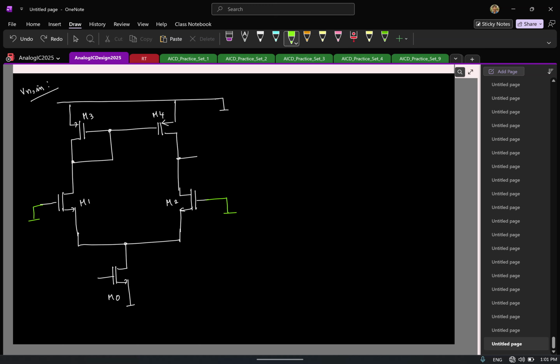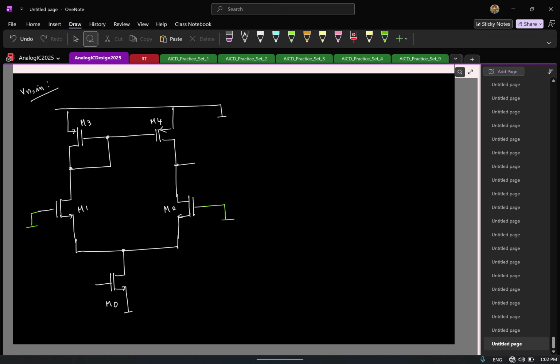Great. So the exercise is the same. How many noise sources are here? 5 are there. So you find the noise from each of these 5 transistors to the output. Here the short circuit current is easy. You find the output power spectral density in the current, and then what you do? You find the gain from the differential input to the current here.